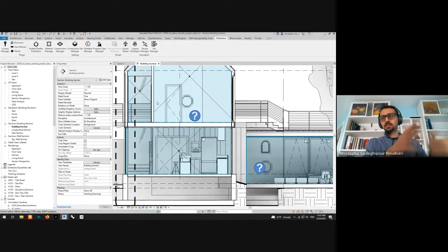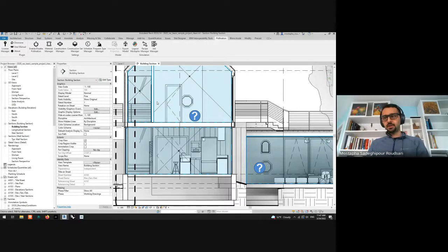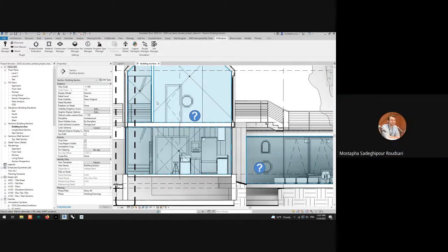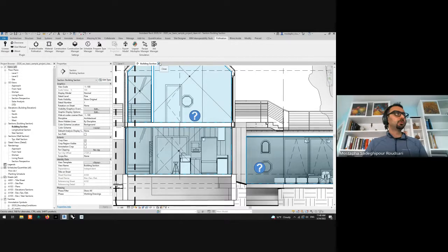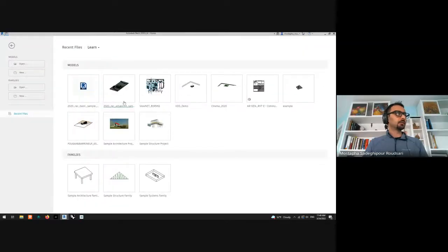We have a few ideas of how to handle it. If you are a Rhino user, we have already shown a script that creates a plenum for you. The other idea is to add functionality inside Revit where you can just type in a plenum height, and we can add a plenum or a way to offset it up and down. But for models where everything is extruded, like the Revit Advanced sample model, we have a better solution. So let me move to that model and then I can show everything else, including what you asked about. I'm not going to save.